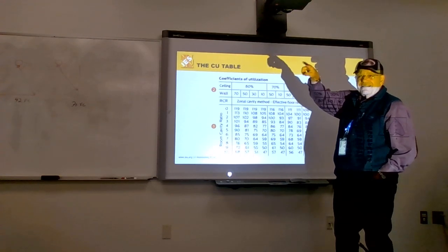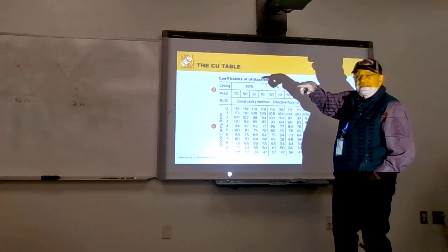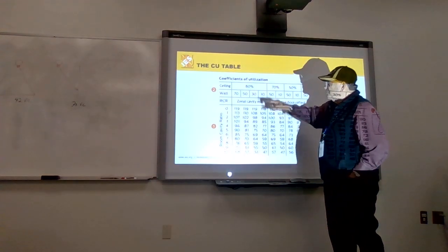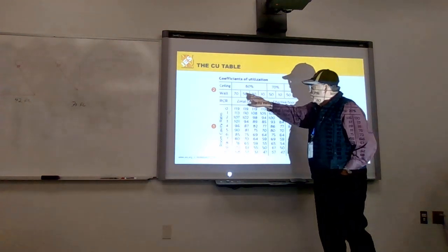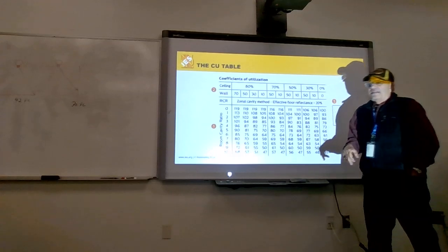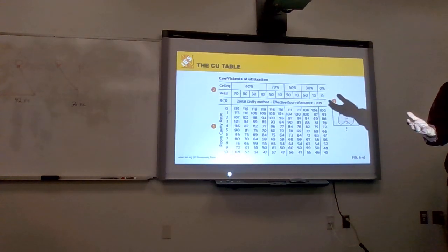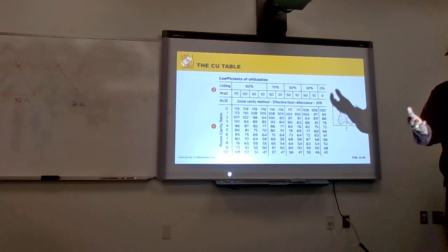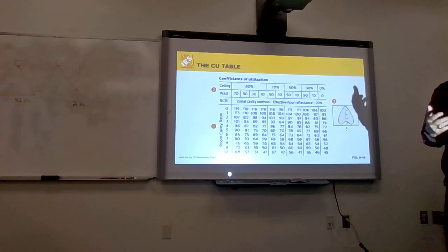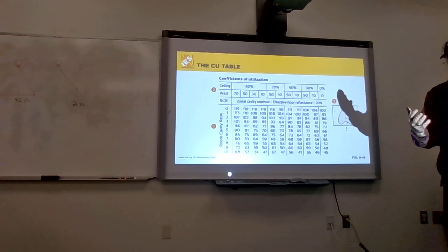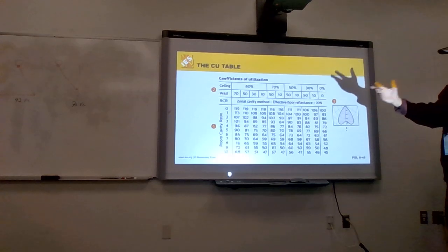That letter that looks like a P, that's really reflectance, so it's 80%. And then we get to choose 70, 50, 30, or 10 reflectance off the walls. What determines that? The paint color, right? Or if we have wallpaper with bold colors or muted colors, it depends.